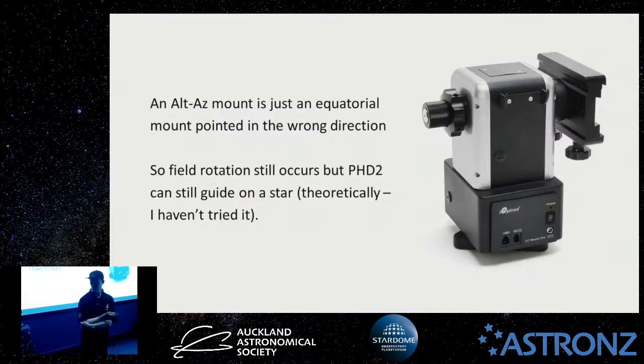Neville's story is actually quite a good one because he did have problems with a couple of motors, and what we did work out is that it was a balancing problem. The way that his OTA was set up, it couldn't be properly balanced, which puts extra load on the motors. Now the ZEQ being quite an old mount, the motor controller and the motor, particularly the current sense on the motor, wasn't very good.